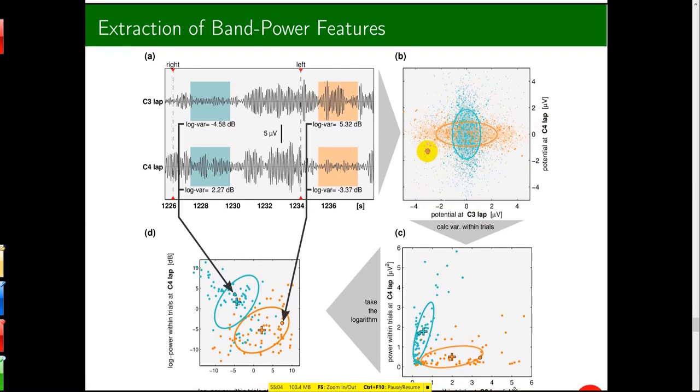The green against the other, by mapping, by projection of the amplitude of signals, we cannot see a difference. Therefore we can just take the variance of all trials, of 100, let's say, 100 trials, and then map it this way. Again, it also shows C3 against C4. And when you take the variance, it captures the difference between two classes. In one case, we have high variance. In this case, small variance. And this can be plotted, visualized in two dimensions like this.